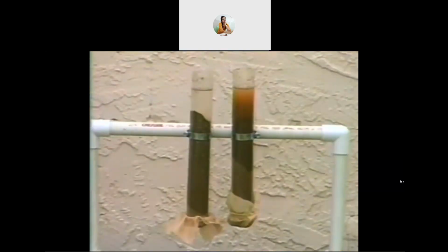Let's look at what happens in the soil when we irrigate. We apply water to the field so that a layer of water is sitting on the soil surface. The water on the surface seeps into the soil, filling the spaces in the soil with water. The longer the water sits on the surface, the more water seeps into the soil. The amount of time the water sits on the surface is called opportunity time.